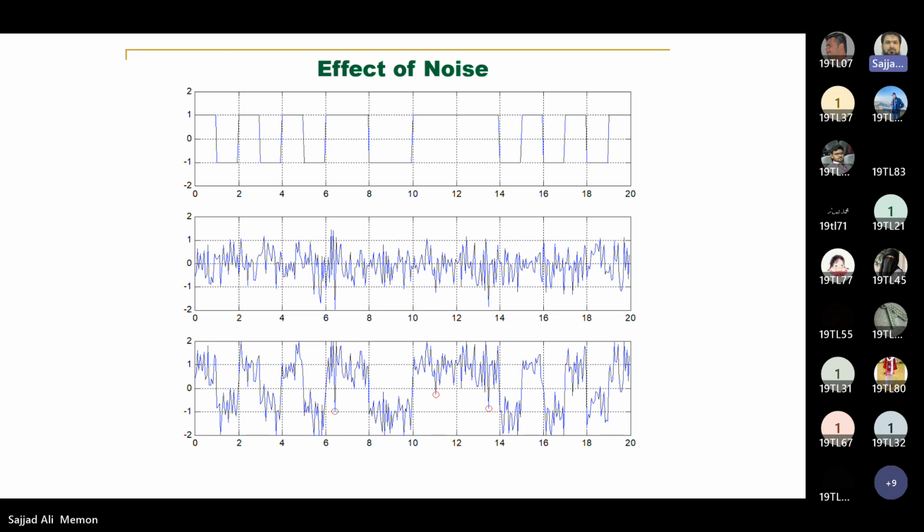Here you can see the actual transmitted signal. This is the effect of noise on the received signal before equalizing. This is the equalizer, which tries to match the signal with the transmitted one or remove any distortion or ISI which is present with the signal. And you can trail from here: 1 0 1 0 1 0 1 again 1 1 0 0 1 1 1 1 1 like that. So you can trail from the signal what we are receiving. The detector, for every sample, will decide whether it is 1 or 0 from these received distorted pulses.